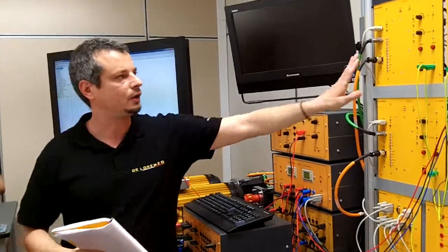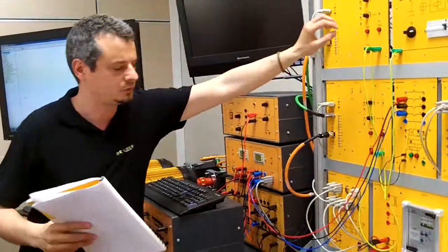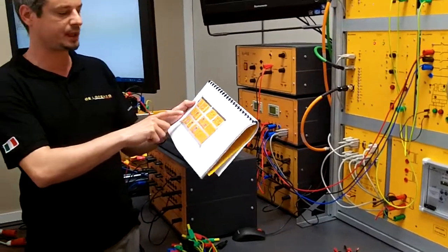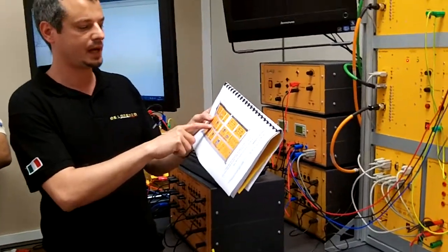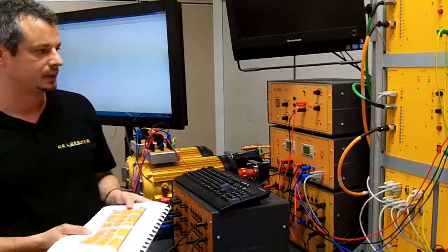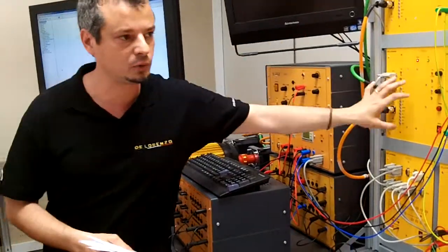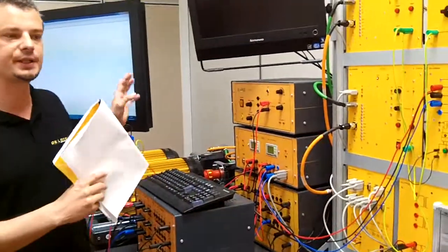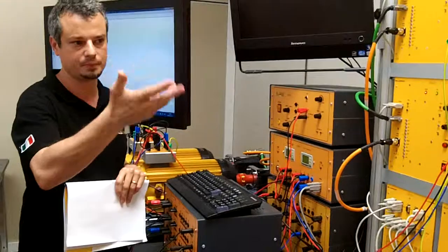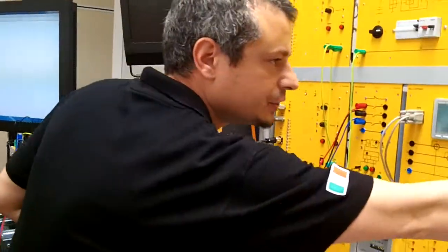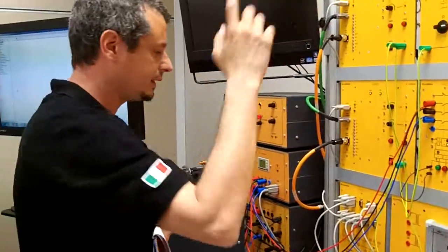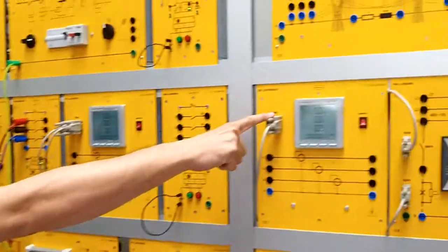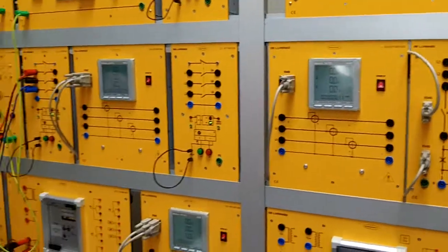Every module has a code on the back or on the side. The code is, for example, channel 1 address 2, or channel 1 address 1, R1 channel. What does it mean? Every module that you receive has an address, because the SCADA software, when you want to talk with this one, uses address 10. Channel is 1. So you have to connect the serial connector to the right channel.